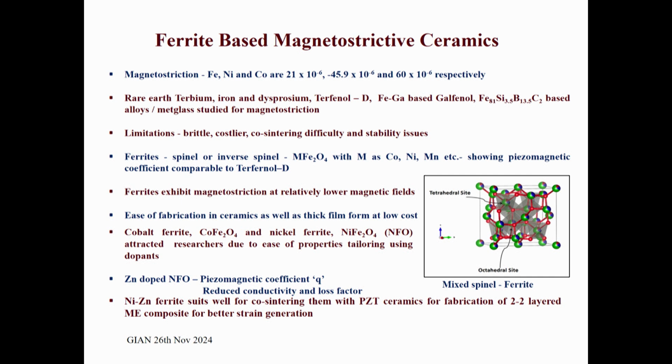But there are certain ferrite systems like zinc ferrite, ZnFe2O4. In zinc ferrite, zinc is non-magnetic, and the magnetic moments of the ions get cancelled with each other. Therefore, it is expected that zinc ferrite in bulk form at room temperature is not supposed to be magnetic. Whereas, in the case of cobalt ferrite, there is a concept which you call cation redistribution. You may not be aware about it, but again I just wanted to mention.